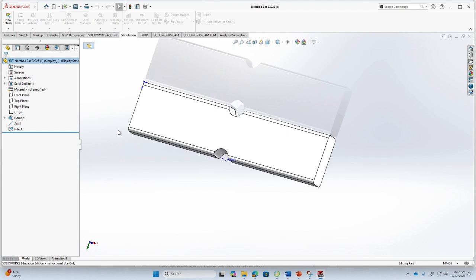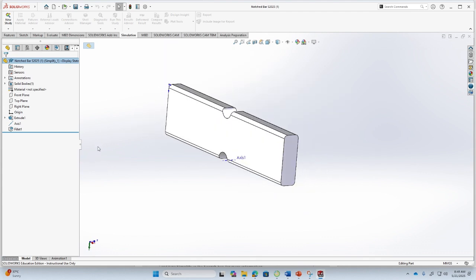What does that mean? In the model, many times there are details which are important from the point of view of giving this drawing to somebody to actually machine, for example, right? But they're not that important from the point of view of stress analysis, right? You can include them, but they're just going to make your model more computationally expensive. You understand the term computationally expensive? Meaning the computer takes more performance load to calculate it. Yes, you need more memory and you need more processor power. Okay? Why? So think about it.